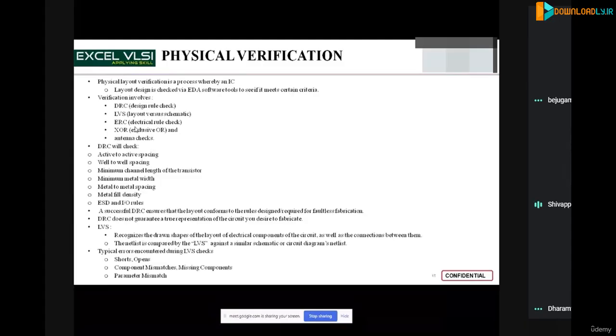That is one thing. Second thing is, any device will be having both combinatorial and sequential circuit. Okay, so that is flip-flops in combination with the gates. You will see all these when you get into STA. In sequential circuits, you are giving a reference clock, and then you are dividing the whole circuit into multiple timing arcs with respect to the clock, right? You will analyze all the timings. That's what the static timing analysis tool does.